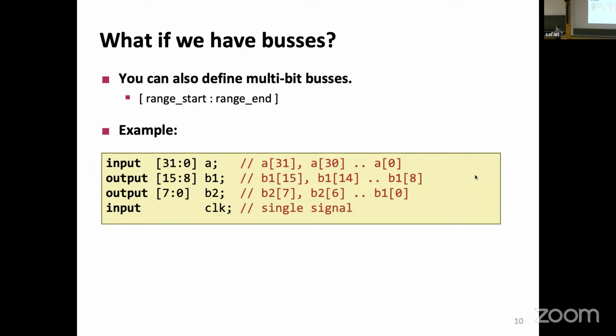At some point, we can say something like the output assign, maybe B equals A. But if you do this, notice that A0 will be assigned to B4, and A1 will be assigned to B2, B3, etc. So although the assignment looks very simple, and in your mind this is a 5-bit value and this is a 5-bit value, be careful.